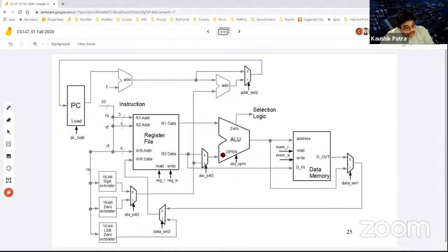That's the main challenge of computing it. And this combination of control signals is called a micro instruction. So in each phase, like instruction fetch, instruction decode, execution, memory, and write back, the controller issues a micro instruction to the data path to act on. Each time it computes a micro instruction and sends it. So in project 3, you'll be dealing with that part.